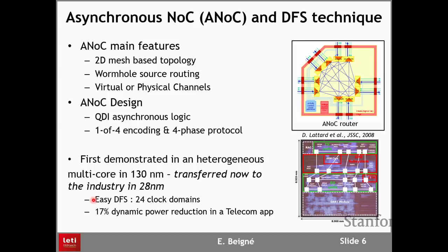What we have here in terms of design is what we call quasi-delay insensitive. It means that whatever the variation due to voltage supply changing or temperature changing, the circuit is always functional. There is one basic hypothesis that we ensure by construction when we design the circuit. We have specific encoding and protocol. This is for the handshake. So you remember that we don't have clock ticks. We have this handshake. And this, we first demonstrated some time ago. We already have a lot of generations of it. And what is really interesting is when you go from one technology to another, whereas in a synchronous circuit, it takes time, it's difficult.